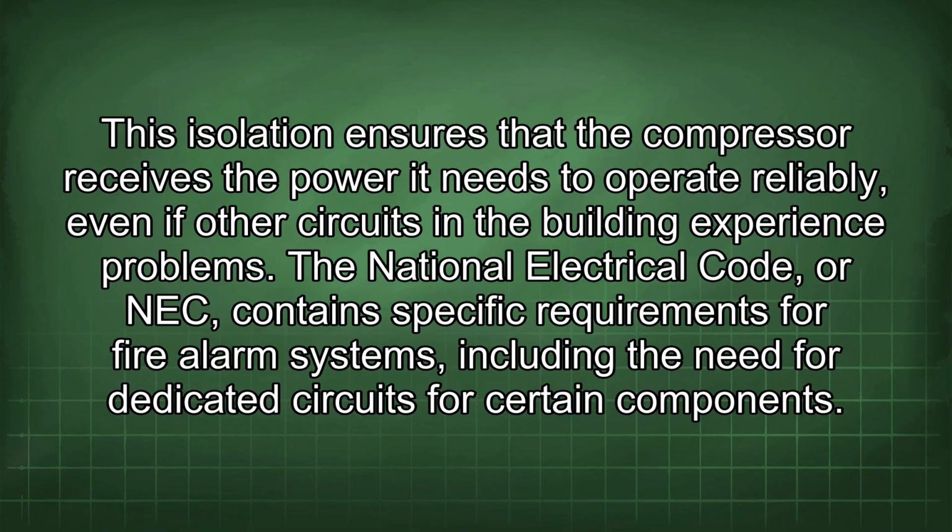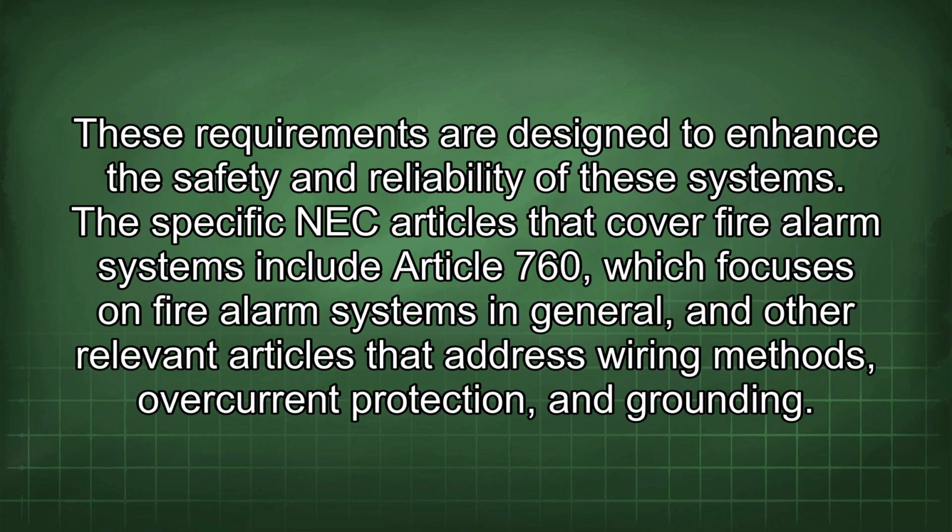The National Electrical Code, or NEC, contains specific requirements for fire alarm systems, including the need for dedicated circuits for certain components. These requirements are designed to enhance the safety and reliability of these systems. The specific NEC articles that cover fire alarm systems include Article 760, which focuses on fire alarm systems in general, and other relevant articles that address wiring methods, overcurrent protection, and grounding.